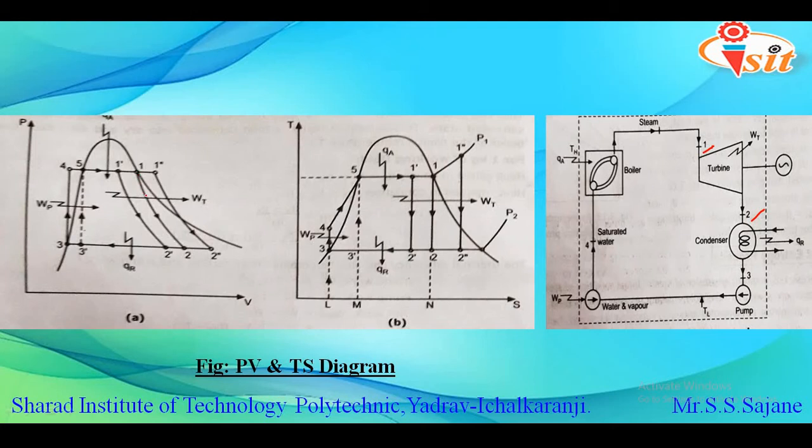In the case of the PV and TS diagram, we can refer to these same numbers. If we consider the line 1 to 2, then it represents the isentropic expansion of steam, which takes place in the turbine. Thus in the turbine there is an expansion process occurring. We can observe that the steam pressure will have a great drop. So this was about the first process which occurs in the turbine.